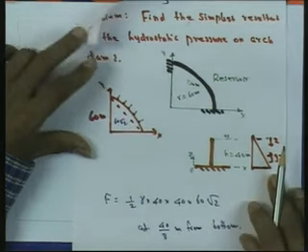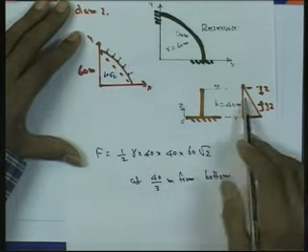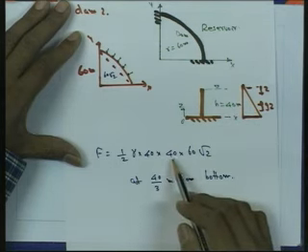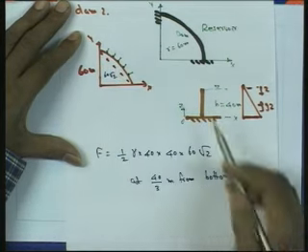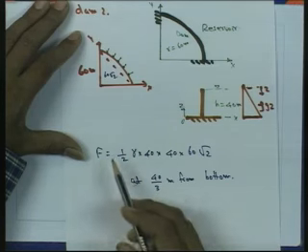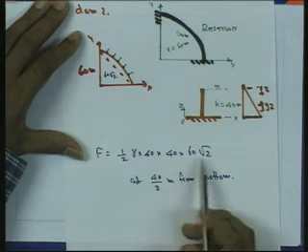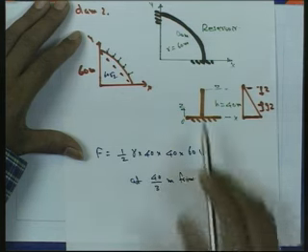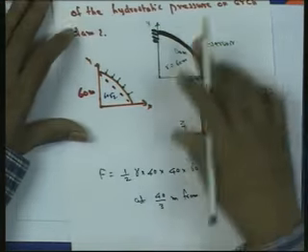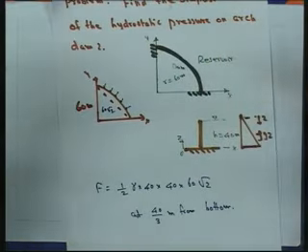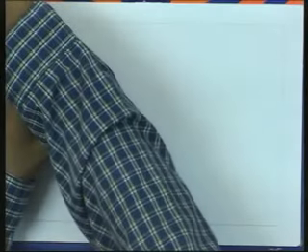So, finally, we can determine the resultant force as half gamma into this 40, which is the height, and then multiplied again by 40 into 60 root 2, which is the area on which it is acting. So, the simplest resultant in this case for this arch dam will be half gamma into 40 into 40 into 60 root 2, where gamma is the specific weight of water, and this will be acting at 40 by 3 from the bottom. So, this is how to find the simplest resultant of the hydrostatic pressure on an arch dam. Now, one more problem we will consider.